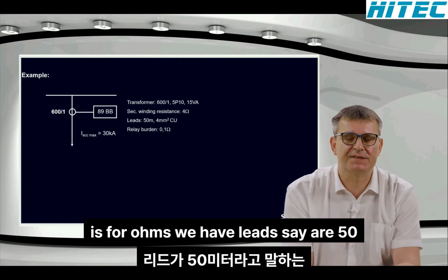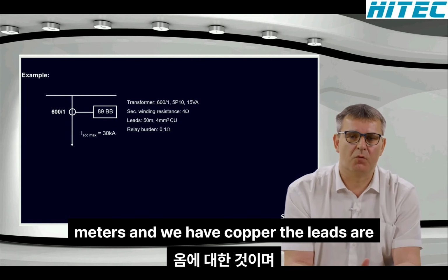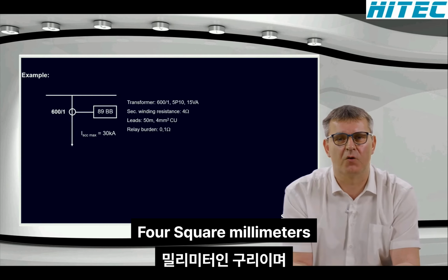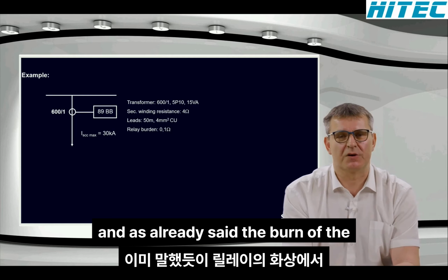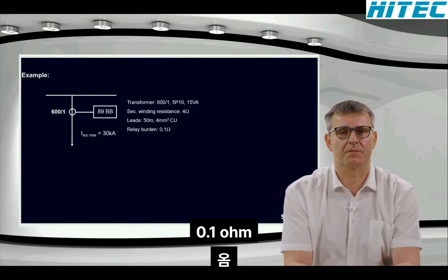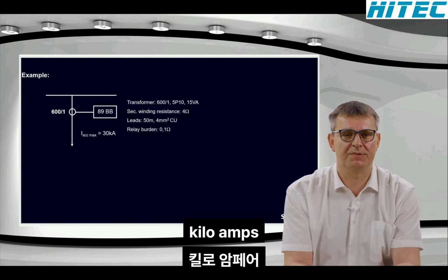The leads are copper, 50 meters, with a cross-sectional area of 4 square millimeters. And as already said, the burden of the relay, the 7SS85, is 0.1 ohm. The maximum short circuit current is 30 kiloamps.